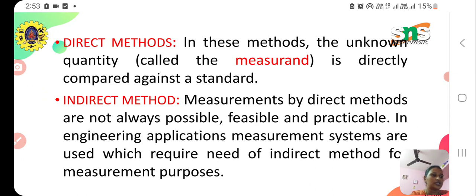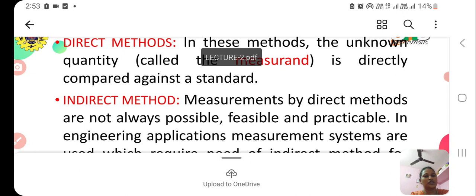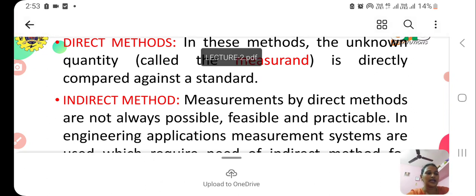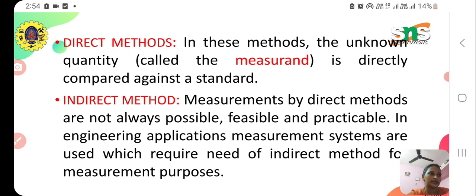With indirect measurements, the dimensions are measured using instruments such as a dial gauge that looks at the difference between the target and a reference device such as gauge blocks and ring gauges. These are also known as comparative measurements, because a comparison is performed using an object with the standard dimensions. The more predetermined the shape and dimension of a reference device are, the easier the measurement becomes. If we have a comparison device with the same shape and dimension as the unknown device, then the comparison and the measurement become easier. But the disadvantage is that the measurement range is limited.